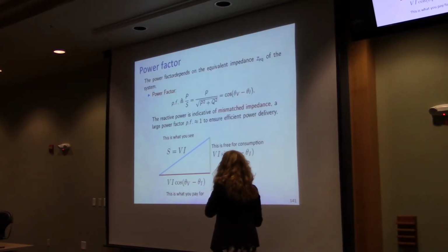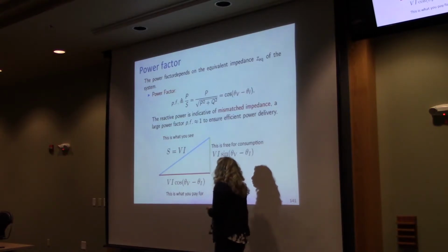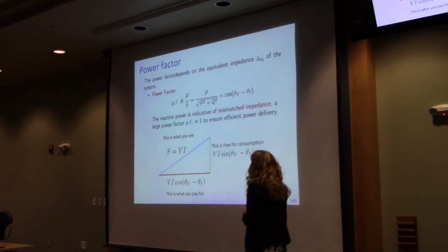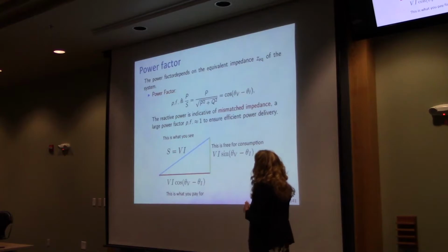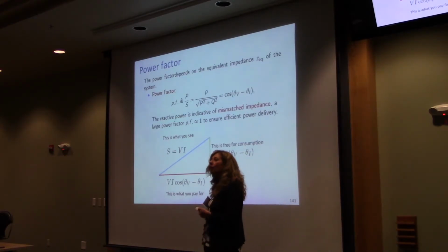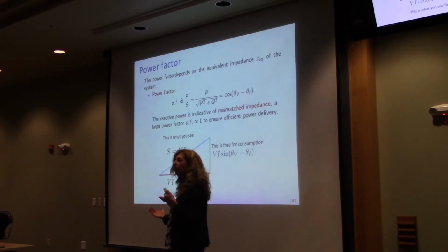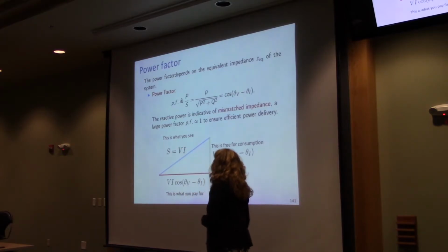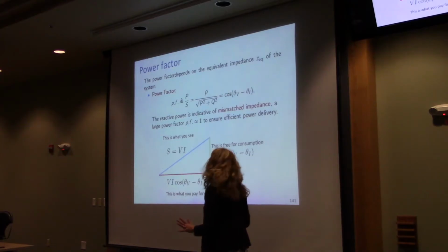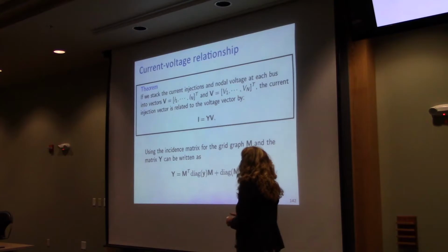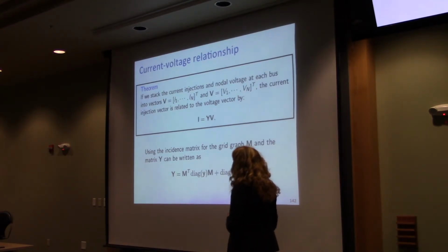So this is sort of the diagram of these different things. And why is this useful? Why is it useful to reason in terms of active and reactive power? There is some information that goes into the reactive power. If you have a lot of reactive power, then it's as if your impedances are not matched. If the reactive power is 0, you have the maximum power transfer. Power engineers cannot match impedances, right? This is not a contained circuit. So what they do is try to control reactive power by having certain places where they can actually control the phases of the AC signal and reduce the reactive power that way. Okay? But we are not going to talk about reactive power at all, because from the point of view of understanding the economics of this, it's actually more important to understand what happens to the active power.